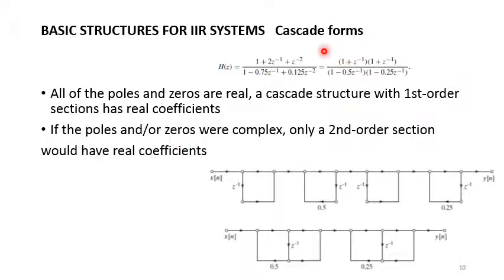Okay, so implementing it, or drawing the signal flow graph, we see we have a zero at 1 plus z inverse. So this is the zero, so we have z inverse, and because this has a coefficient of 1, it is scaling by 1, so we normally do not mention it here. Similarly for the 1, so this is for the first part.